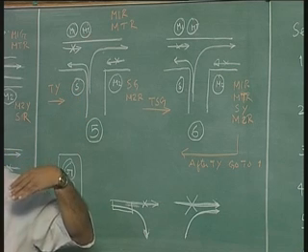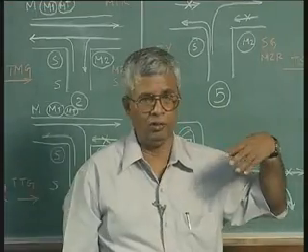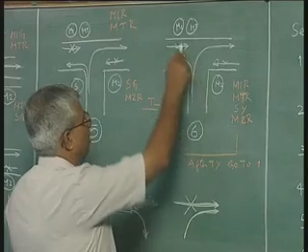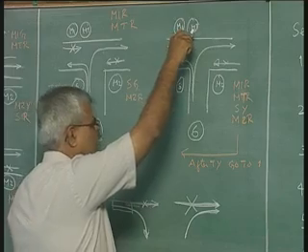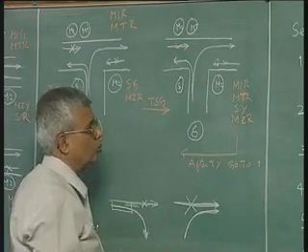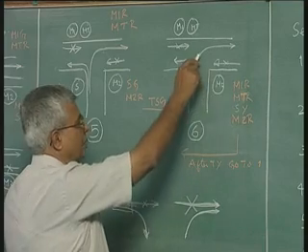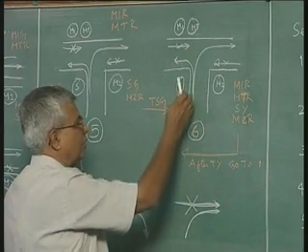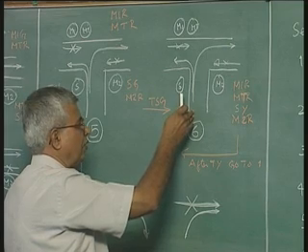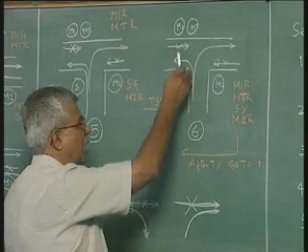It has to be made yellow first and then red. So, in this condition this continues to be red, this continues to be red, but side becomes yellow. Once it is yellow, the traffic here will have to prepare to stop.